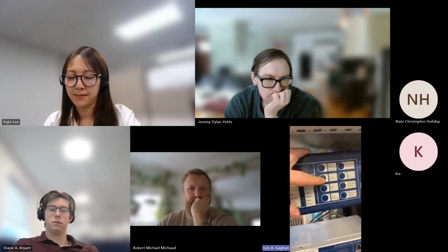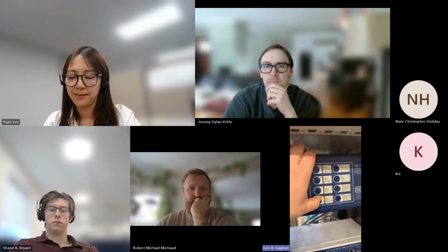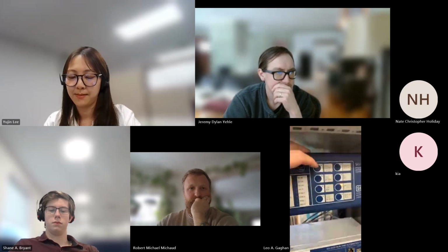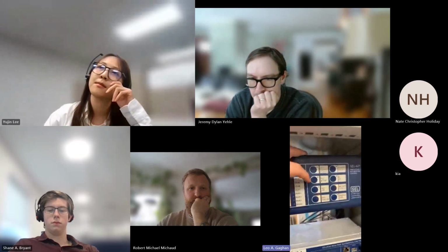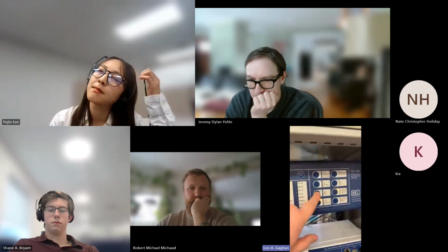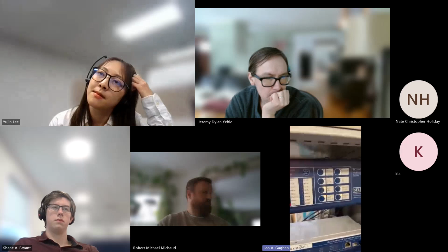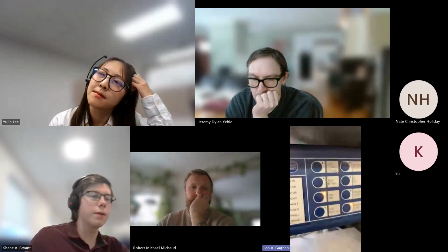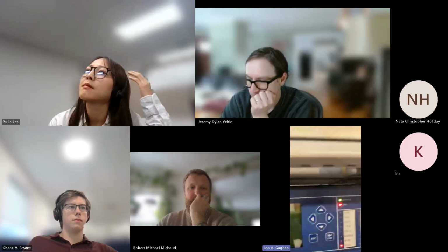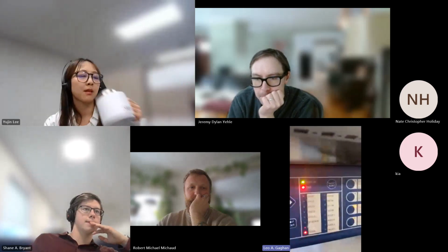Why don't I put it in test mode? You can see that blinking. And then in test mode, I'm going to give it a test trip. With that test trip, we can see here our LED for test trip latched in, letting us know that trip was in fact a test. And we can also see this test LED right at the top here, that latched in. You can see the breaker opened, and you can see it here on that LED, but you can also see it down here on the control switch.